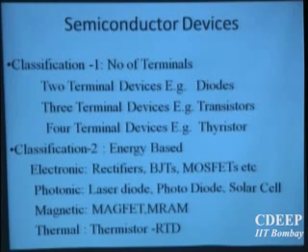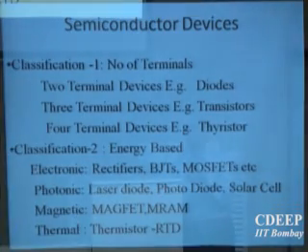And there are 4-terminal devices also available. These are called thyristors, PNPN or NPNP. These have 3 junctions, and therefore 4 terminals. Where do you use thyristors? Anyone? No idea? Another name for them is silicon controlled rectifier, SCR. For almost all power control in power electronics or any such power-based systems, you will require SCRs, or what we call thyristors. They are power devices.